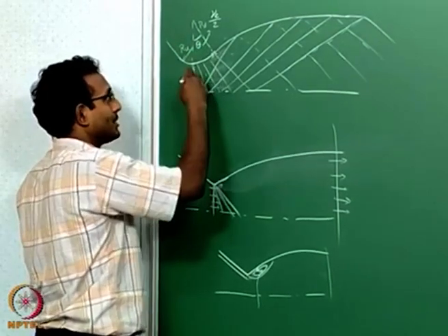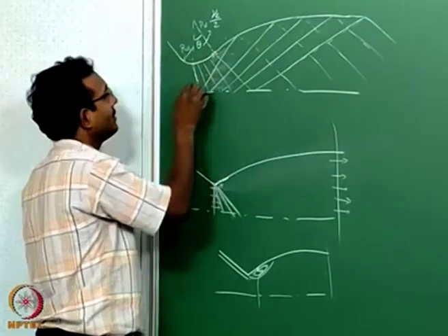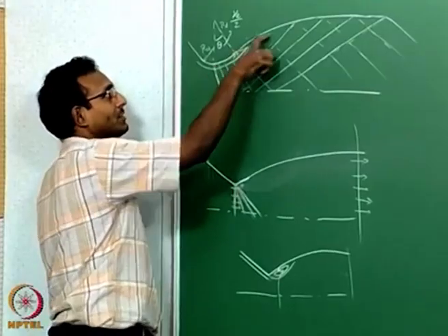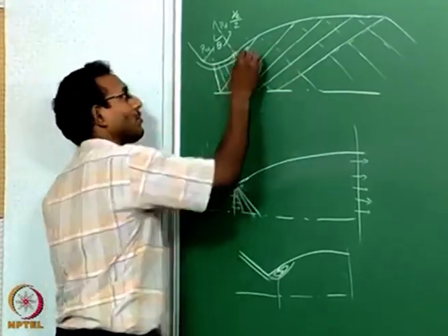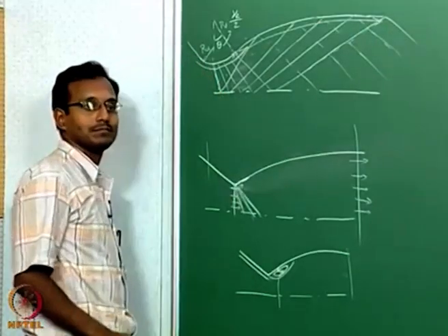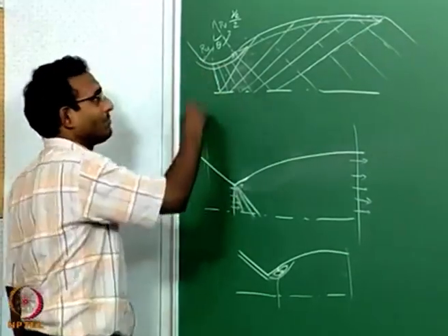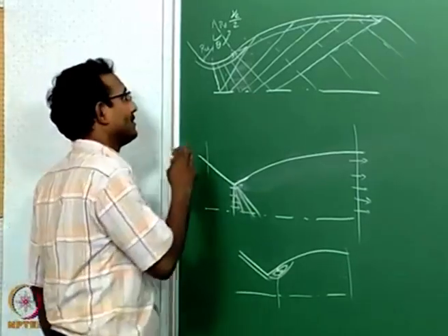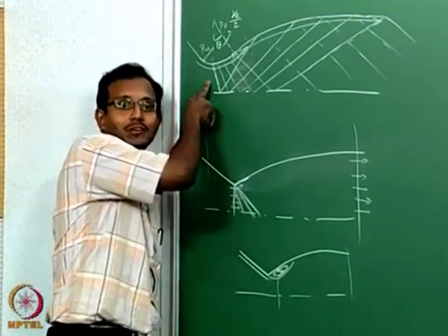Now it will just be expanding smoothly and slowly, so that the flow sees only small turns at any time. It is going to turn slowly, follow the wall very nicely, and finally come to the exit value there. This is what you will get finally. So this is a good thing. If I think about it this way, it is a better way of designing a nozzle.